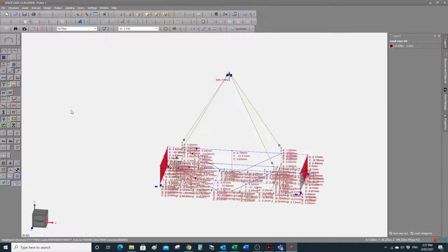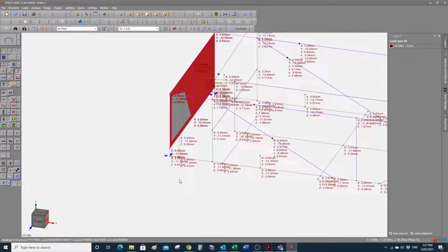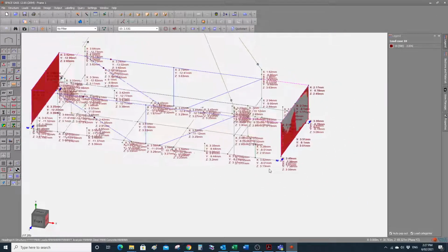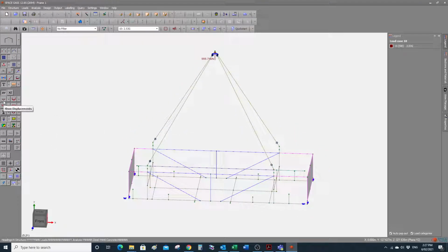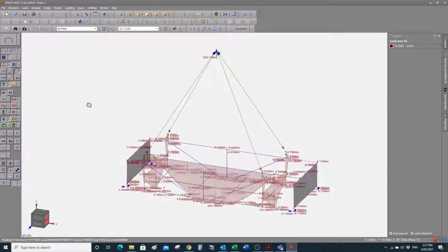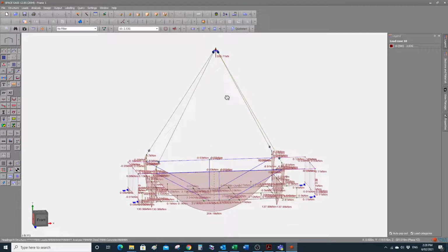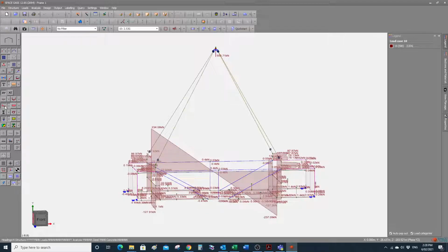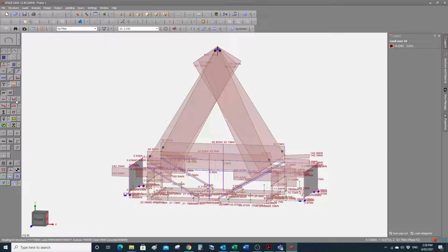And if we look at the deflections or deformation, you'll see there are pretty reasonable deformations here in the structure that now we can rely on. Another important thing that we have to check is the bending moment in the slings. So we see that there's no bending moment in the slings, so basically our release worked well. And also, of course, shear force, we don't have any shear force, and axial force, we have axial force in the slings.